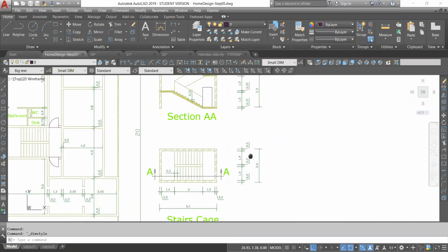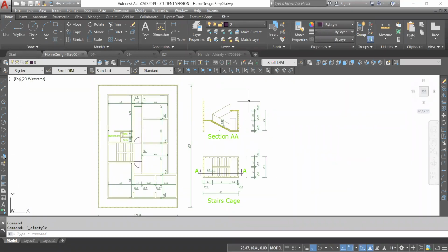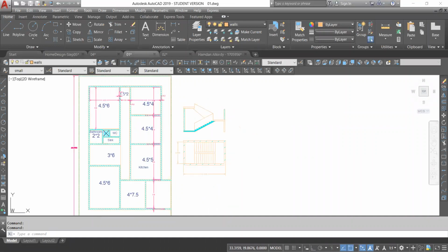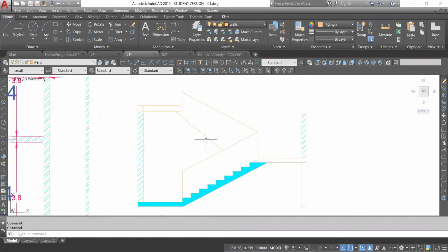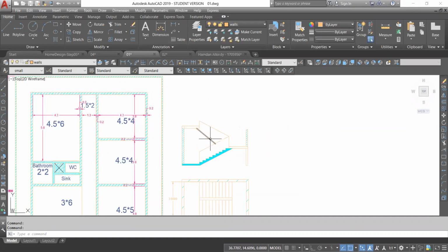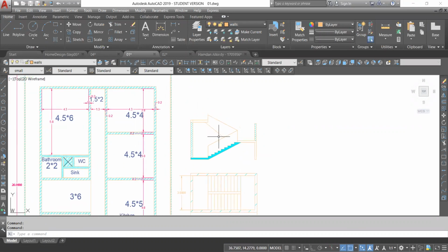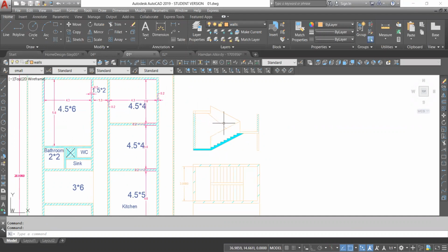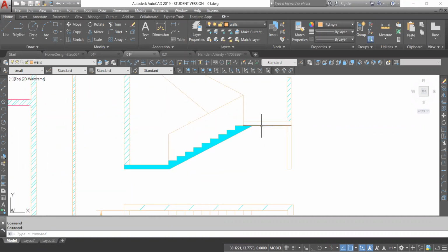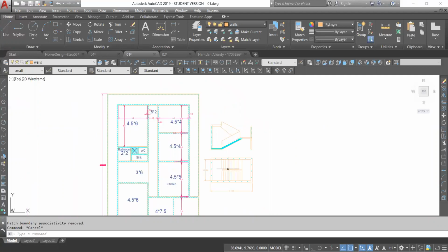So control these properties and try to draw dimension on the same line using align dimension. If I look to this drawing here, it is completely wrong. You can see that the line here is not engineering drawing. This one, we draw a line as you want. No, it is completely wrong. And here, this line must be here, not here. And when you hatch this area, the hatch is not correct. The drawing is not correct.